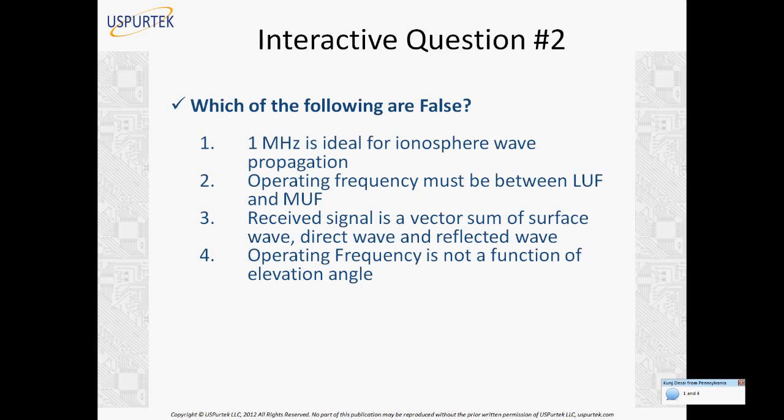So even if we forget everything about skywave propagation, we have to remember that we do have to make a decision about the operating frequency. That is what is of practical use to us as an operator. I must know what my operating frequency is. I am at a certain location, my transmitter is at this location, the receiver is at a different location, and I want to know what my LUF is, what my MUF is, what my boundaries are, and what my operating frequency is in between these two boundaries at a specific time of day, time of year, or time of the solar cycle, and so on. And for that, I have to depend on various sources.